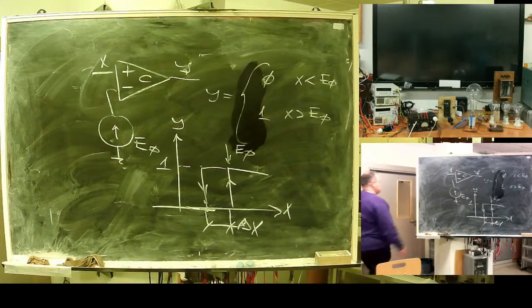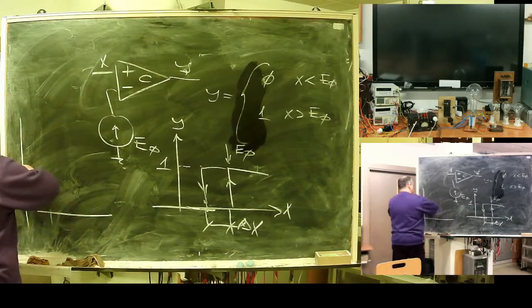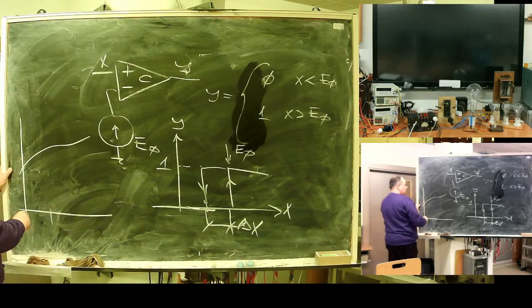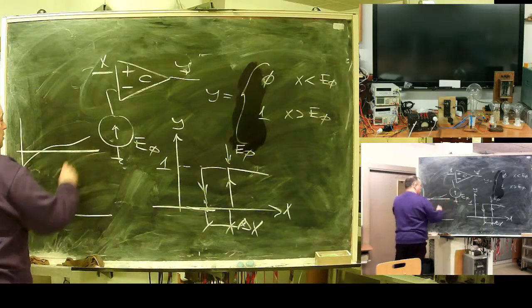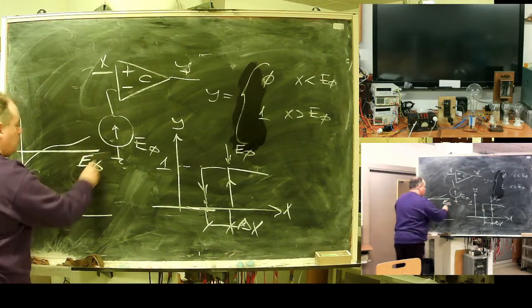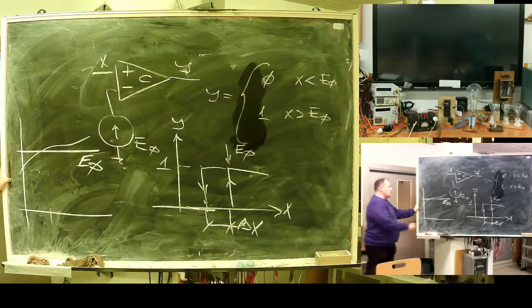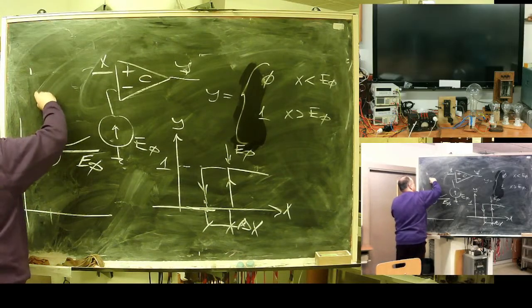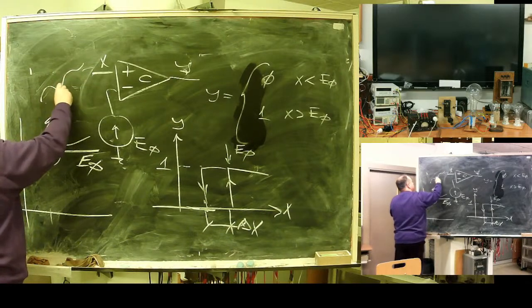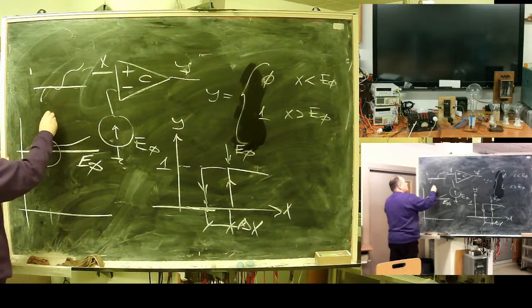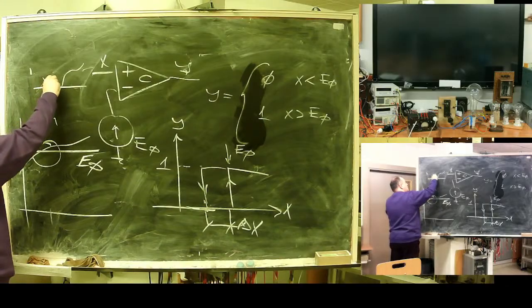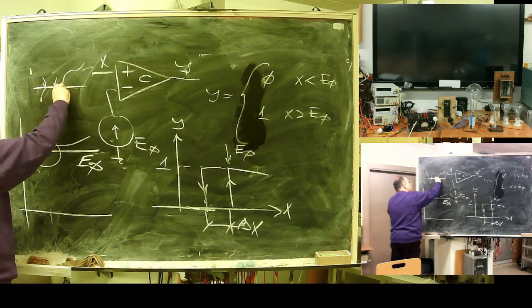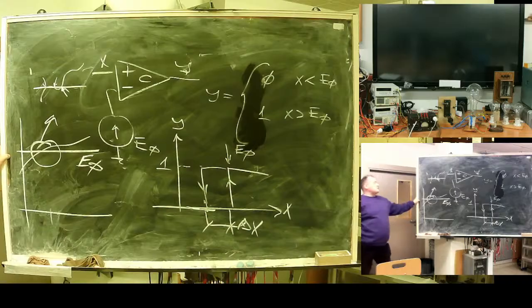To prevent jitter. If a nice signal is at the threshold level and you magnify, what will we see? This will produce multiple triggering.